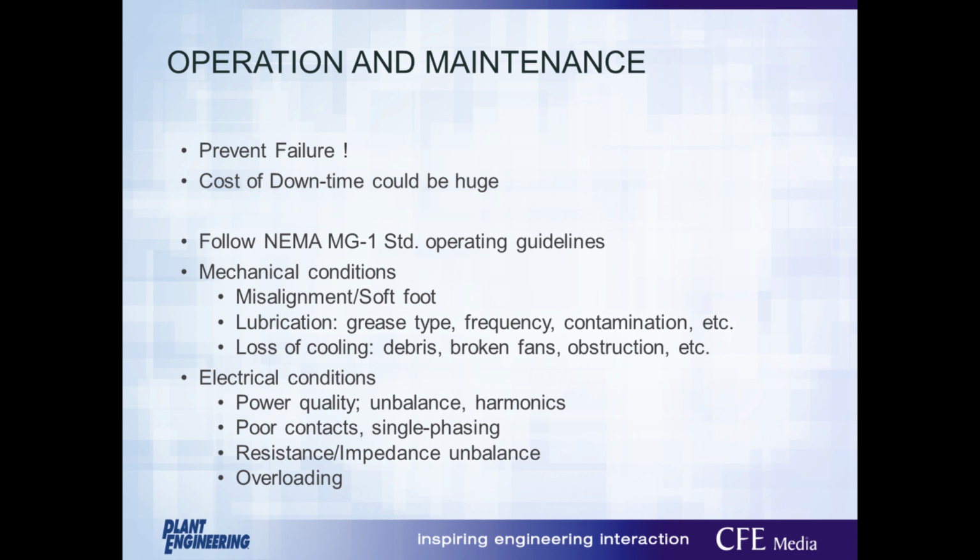Additionally, you want to keep the motor bearings well lubricated. Bearing failures are the leading cause of motor failures, and we'll see that in a second. We've got a nice chart to show you. Grease the motor bearings at the recommended manufacturer interval, and be sure to use the proper type and amount of grease recommended.